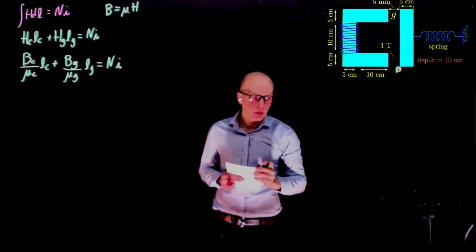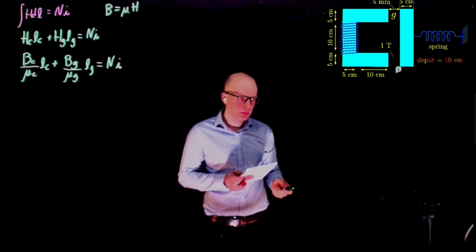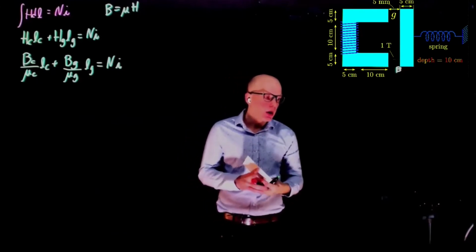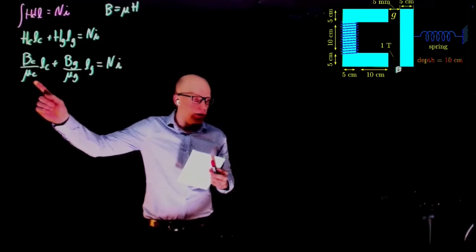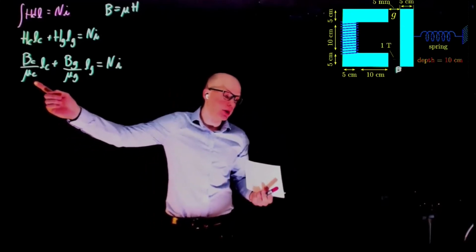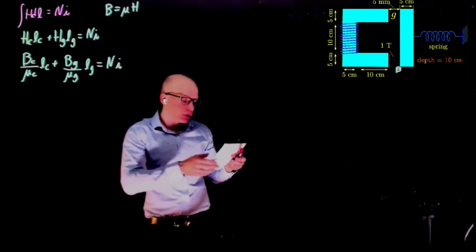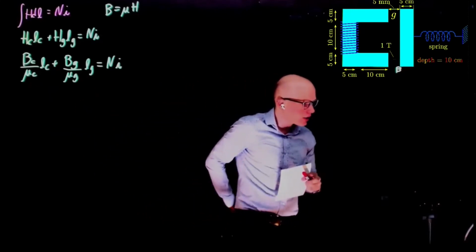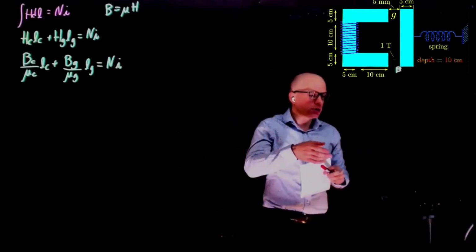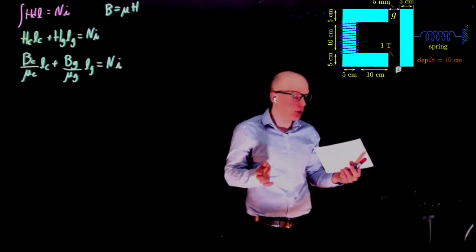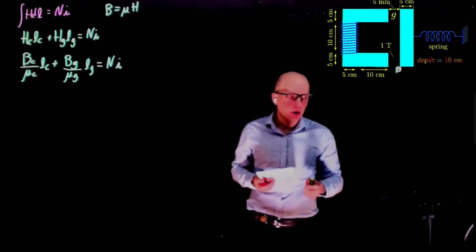I have a question. Yes. Shouldn't you multiply the permeability by the permeability of free space, 4 pi times 10 to the power of -7? Yes. Mu C is the absolute permeability, which is the relative permeability times mu 0. But we are given the absolute permeability. The question gives mu as 1.5 times 10 to the power of -3 Henry meters to the power of -1. That is not the relative; relative doesn't have a unit. This is the absolute permeability already. Okay, so that's not required for this question. Yeah.